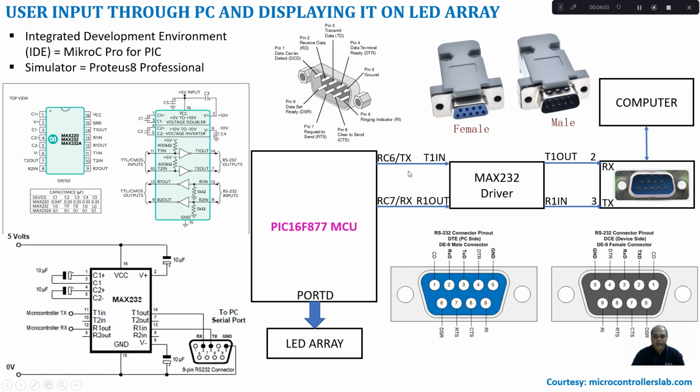These two pins interface with the MAX232, and from the MAX232 the T1 out and R1 in connect to the DB9 connector, which is connected to the computer.